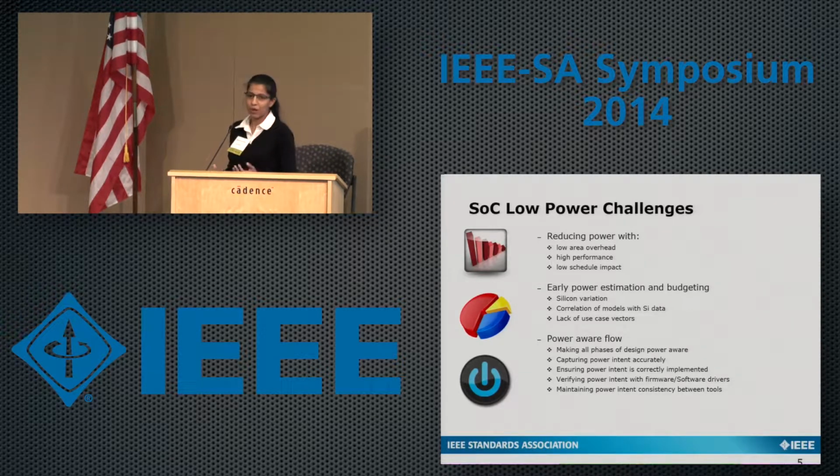And also the bigger problem is dynamic power is a big function of your use cases. On a typical cell phone, we have these standard check marks. What is your power when you're in off mode? And that's the mode when your phone's idle doing nothing. And then you have like 3G voice, you have MP3 decode, you have video decode, and we have these different use cases. And our goal is to deliver a certain power for a given use case.